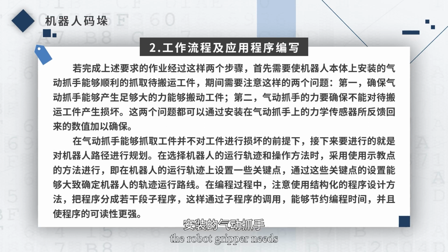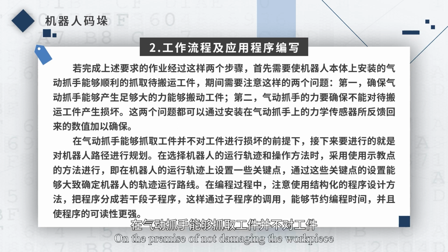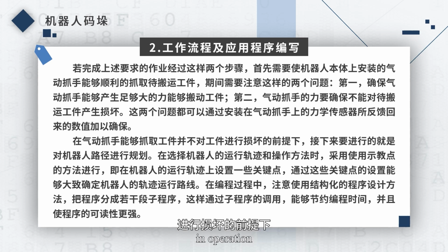First of all, the robot gripper needs to be able to grasp the workpiece smoothly. Care needs to be taken to ensure that, firstly, the pneumatic gripper is able to generate enough force to grasp the workpiece, and secondly, the force of the pneumatic gripper must make sure that it causes no damage to the workpiece. Both of these issues can be adjusted by the values returned by the mechanical sensors. On the premise of not damaging the workpiece, the next step is to plan the robot path.